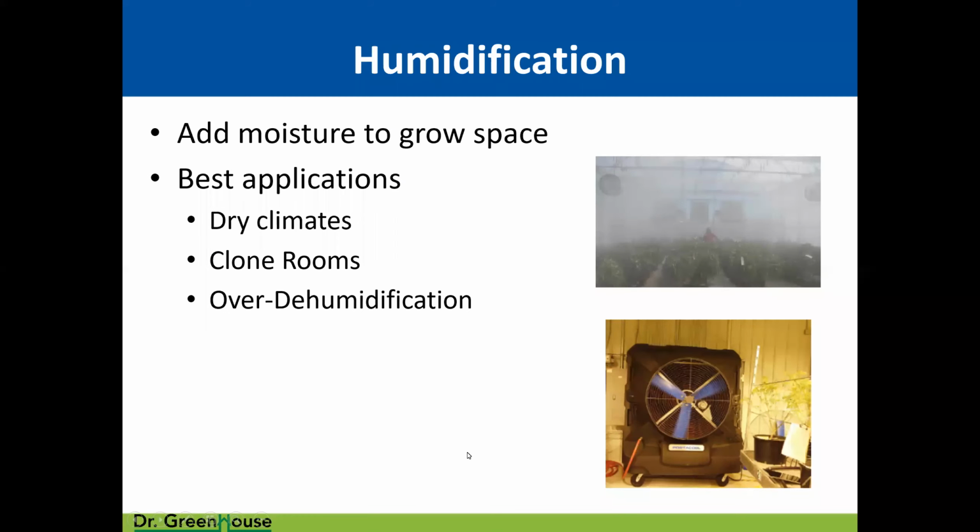And I'm going to say over dehumidification. Some of the air conditioning equipment that's out there now doesn't have variable speed controls on some of their compressors or their fans. And so they've only been looking at, okay, we need to hit all this dehumidification when the lights are on and the plants are pumping. And then what happens? Then the lights turn off and we still need some dehumidification because your plants are still breathing. And now that system can't turn down, and we over dehumidify the space,